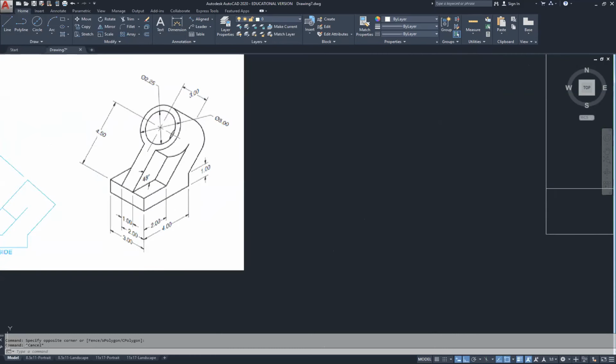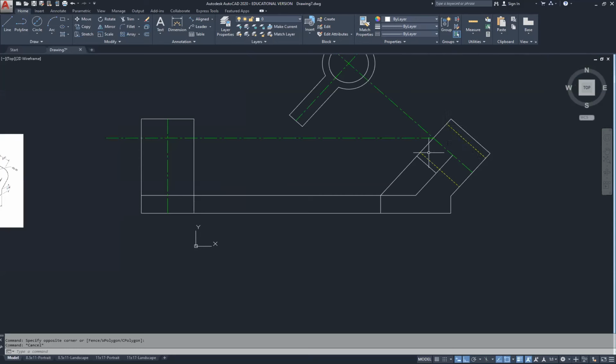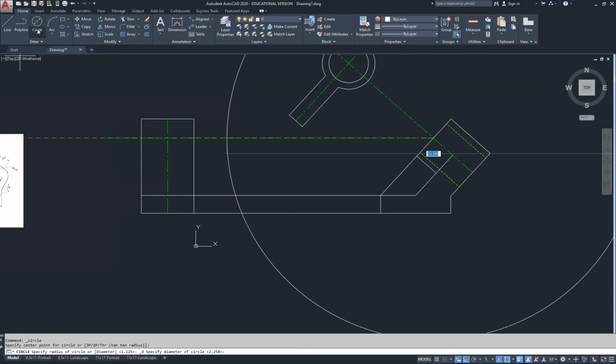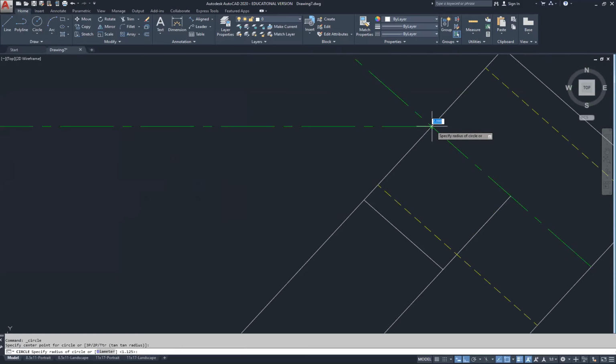So I'm looking at this front view on the auxiliary face, and I'm going to need to draw that circle. Now I know from this end to this end here is going to be my circle's diameter. But from that center point going to the top, the view is going to become squished. It's no longer a perfect circle. For example, if I have the circle drawn here, let's go ahead and change that to radius. This is just an example. You do not have to do it.